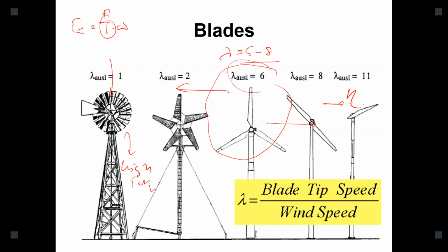There's one example. If the wind rotor is in this direction, you can think of it as a two-bladed one. Then the wind rotor is in this direction, and the tower axis is in this direction. Then the moment of inertia of the rotor is very, very high, so it cannot rotate in that direction. If the wind rotor is in this direction, the moment of inertia is very low, so it can rotate very easily. You can see that the moment of inertia of the rotating mass around the tower axis varies quickly. Due to that reason, large two-bladed wind turbines cannot yaw. That's the main reason two-bladed wind turbine rotors are not used for large-scale wind turbines.